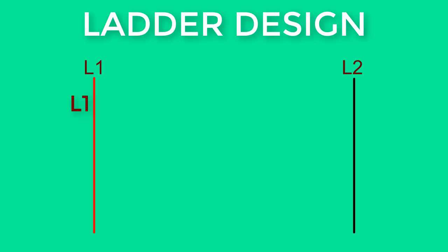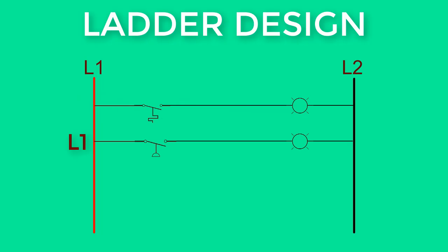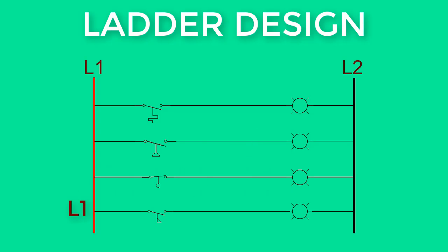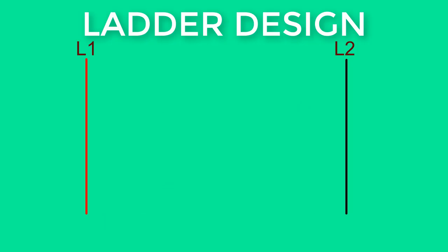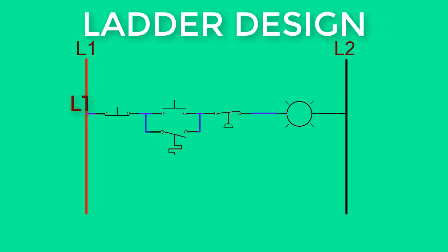Interpreting ladder diagrams is very important. A ladder diagram consists of two parts, the load, and the devices that control the load. As shown here, no control devices are connected between L2 and the load component. Circuit design typically places all load controlling devices between L1 and the load. Ladder diagram design, interpretation and troubleshooting centers around the circuit path of L1.